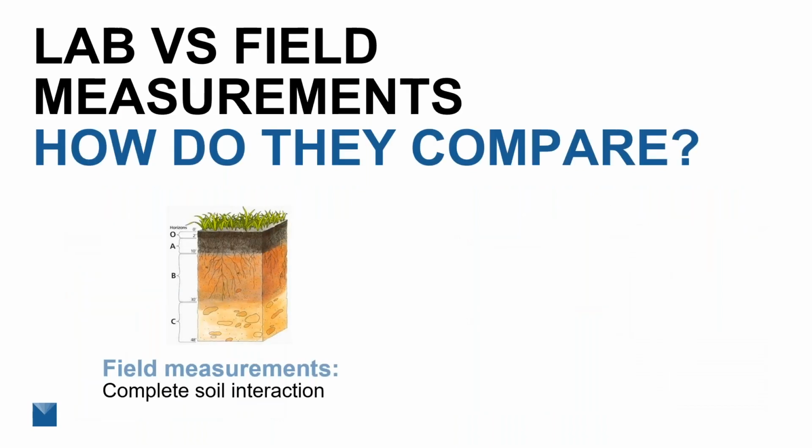So one of the common questions that we get, and a common issue that people run into and we see in the literature, is how do lab and field measurements compare? Well, when we're thinking about field measurements, it's really a complete soil interaction. We're measuring how the water's moving through this entire soil profile to an extent. And really, one of the main things controlling that is whichever layer is the most limiting layer. But this really gives us the best idea of how things are interacting in the field.